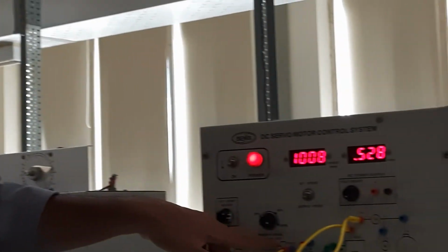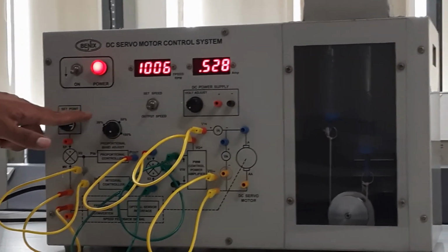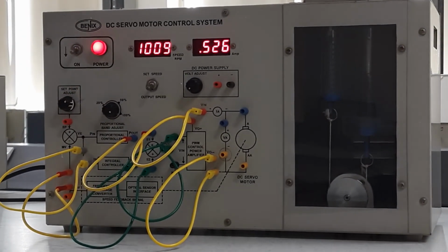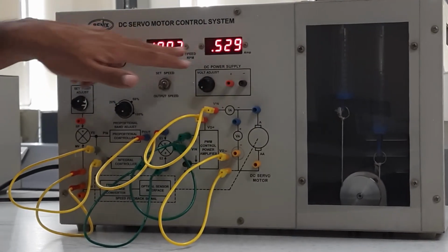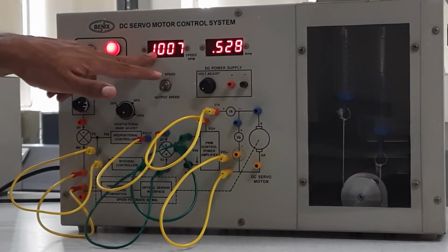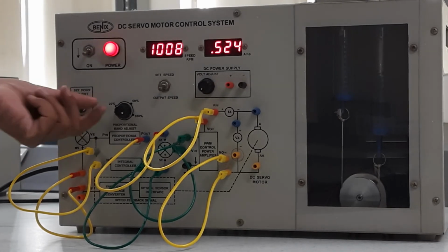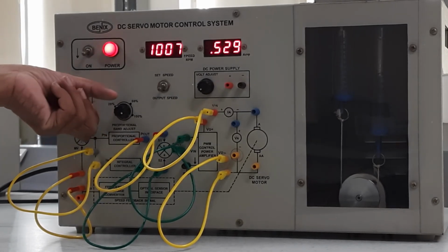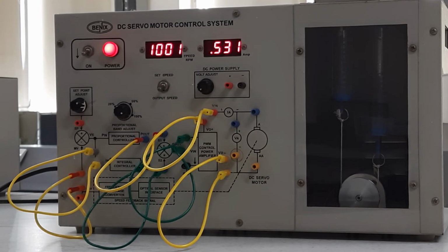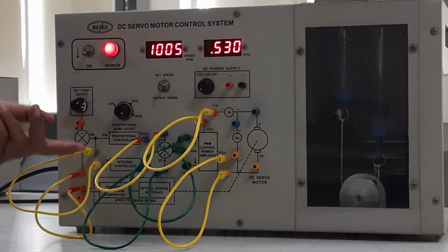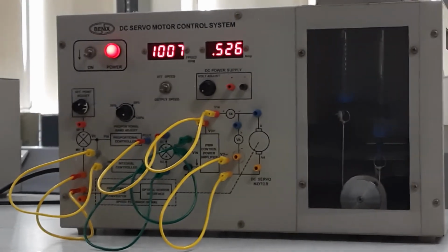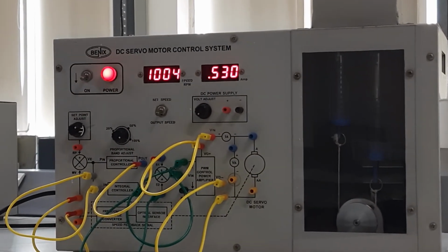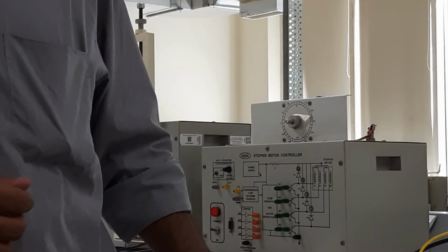First, keeping the proportional controller with gain as 20%, you will provide a load torque and monitor the armature voltage, armature current and the speed of the machine. Then similarly you change the gain to 50% and then to 100%. So 3 tables are done. Similarly, the next set of 3 tables will include the integral controller also. Again you will repeat. So there will be 6 tables, and you will be plotting the speed torque characteristics and back EMF characteristics for this particular experiment.